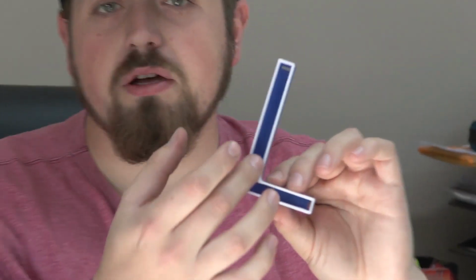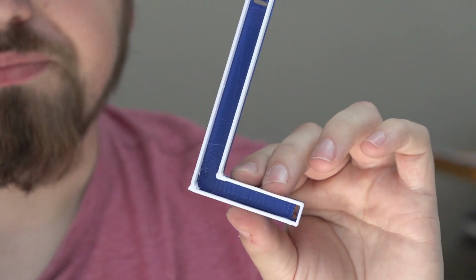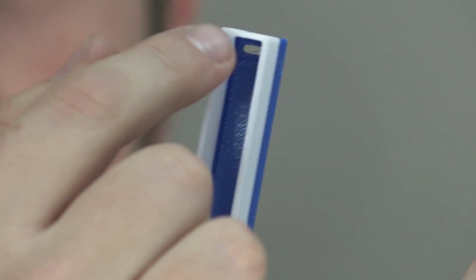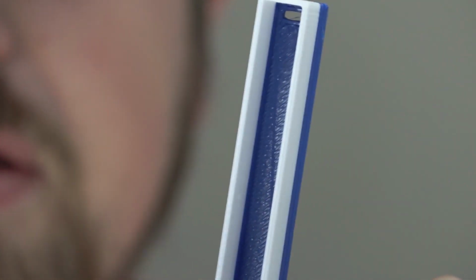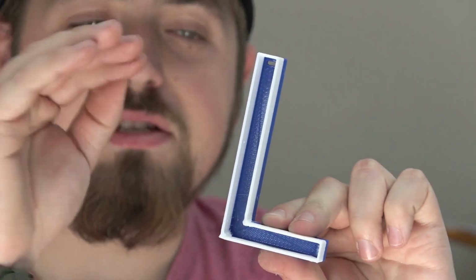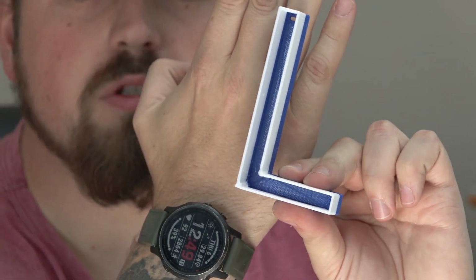But all in all, we want to look inside here and explain what we've done. Here at the top we have our slit, our cut-out area, and here at the bottom as well, and that is purely for our LED strip to enter from behind. Let's say for instance this was on a board, and inside the board has all your electronics. You're going to feed from behind the board through into your letter, put your LED strip down here, then across here, and then back into that hole and back into the board, which will continue to the next letter. And that is basically how you are going to do the LED strip.